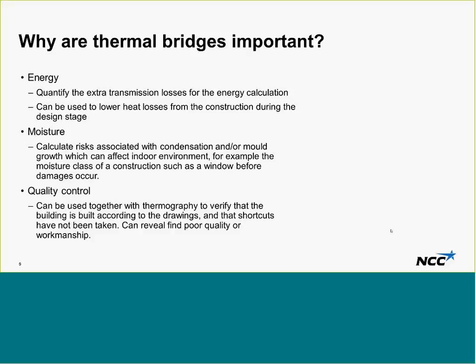And thermal bridges can be used as a sort of quality control if you use thermography. And to verify thermal bridges after the construction phase, you can see using calculations and thermography which thermal bridges are supposed to be there, which temperatures should we have, and if they vary a lot with the thermography, you may have a situation where there has been some kind of cheating going on, or they forgot to put insulation in, or maybe other problems like wet insulation materials.